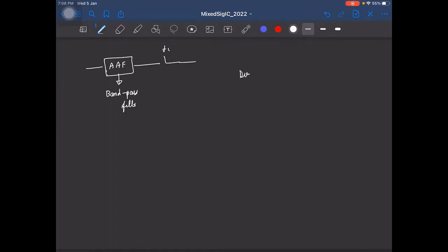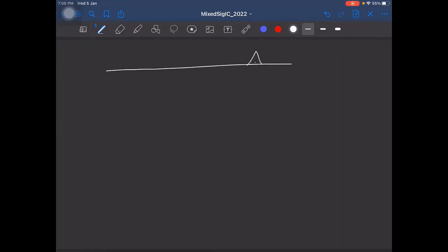And this scheme is also known as direct RF digitization, right? Because you are directly digitizing the RF signal, by directly down converting it as well. Okay. Now let's take it one step higher. So we saw that if we have this RF signal here, something like this, minus Fc and Fc.